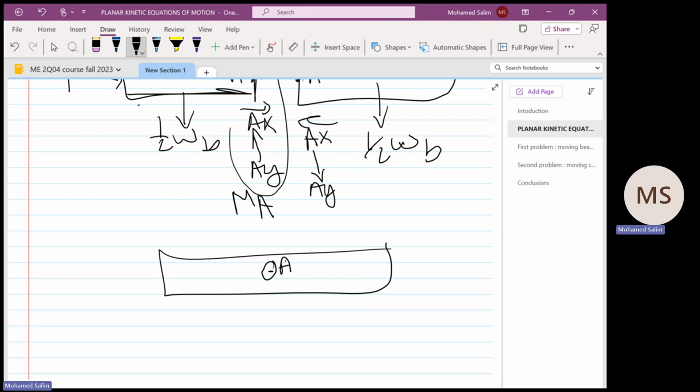Ask yourself, we have a resistance, we have a force. We have a resistance to rotate, we have a moment. Here, we have a resistance to move. The beam can rotate. It can move in X direction, or Y direction, or Z direction. So we have forces in X, Y, Z if you have a 3-dimension, or X, Y if you have a 2-dimension.